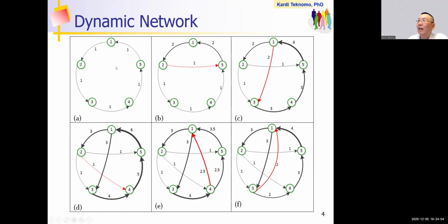So you will see I add one link, the capacity is still the same, but because I add one link, the flow here will increase over time. This is more congested than ever. So adding a link can actually increase the congestion level in the long term. Now from this network, what will happen? I add another link here, randomly. Compute the IFN again, and you see now this is the most congested. Remember, we keep the capacity the same. This now becomes 4 times than earlier. So you keep adding links, and apparently you keep adding congestion.